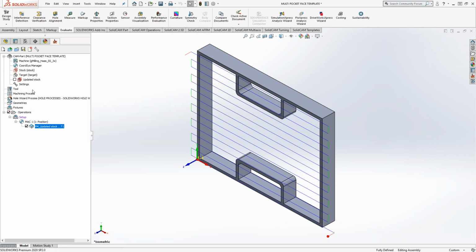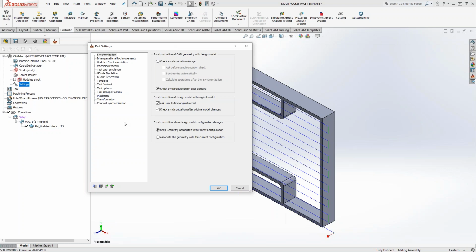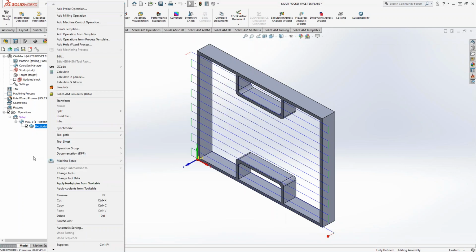Yes. So that's exactly what I was going to do. So if you guys already talked about it, I'll just briefly review it for anyone that wasn't in attendance yesterday. In your part level settings, or even in your global settings, when you go to template, you can load those templates as well. So if you had a small minor change, like an offset that you'd like to default to every time you open up a particular toolpath, or even just a full toolpath, you want your face mills to always be done with tool number 1 or something like that, you can check this box, and then this becomes a preloaded template. Every time you load that particular type of toolpath, it will load that template instead of just the default.